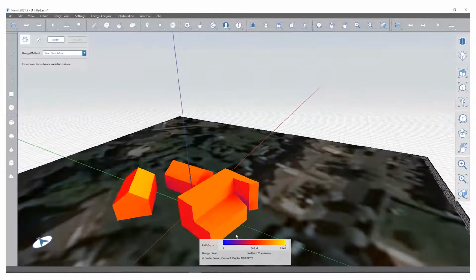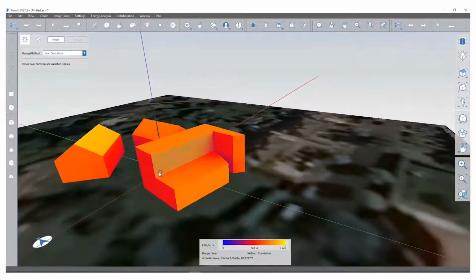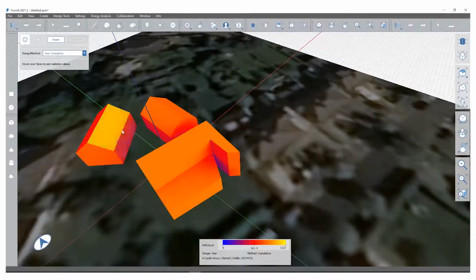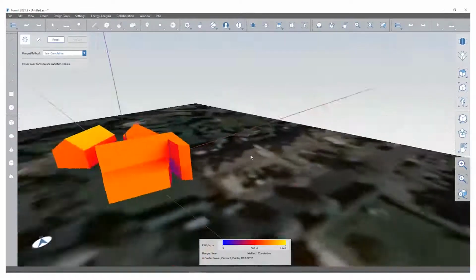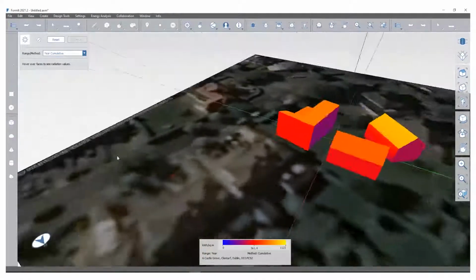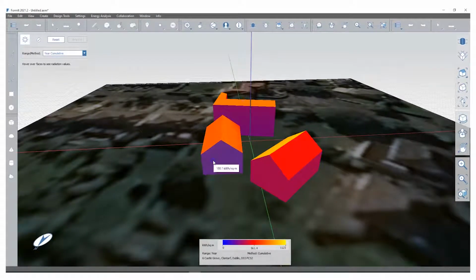So if you're getting too much sunlight on the front facade, if you've got a lot of glass, you might want to put shading. Or if you're going to put solar panels, which facade are you going to put them on, and maybe you can edit a different roof to suit that as well. And we can see here that it's going to be quite a low impact of sun on the rear facade, so you might put fewer windows or less glazing on that side as well.